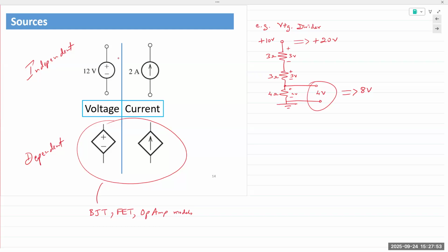All right, so what makes it a current source? Nothing except the mode of operation. The benchtop supplies that we see in front of us, or at least behind you on the lab benches, are both a voltage source and a current source. If you run a source in constant voltage mode, it's a voltage source. If you run it in constant current mode, it's a current source. That's it. There's no other difference. So benchtop supplies, the PSUs that we have in all the labs, are voltage as well as current sources.